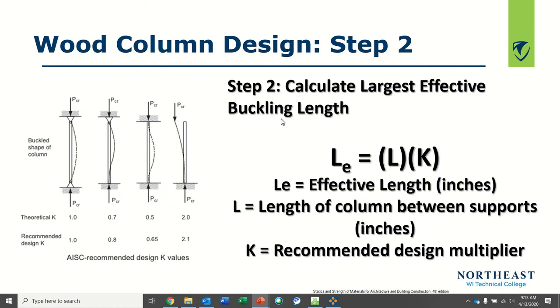Step two, calculate the largest effective buckling length. My LE equals L times K, because I'm going to assume two pinned ends, it's just going to be nailed, so K equals 1.0.